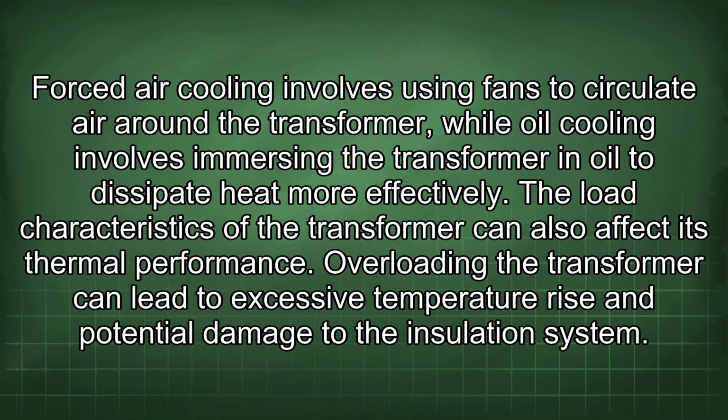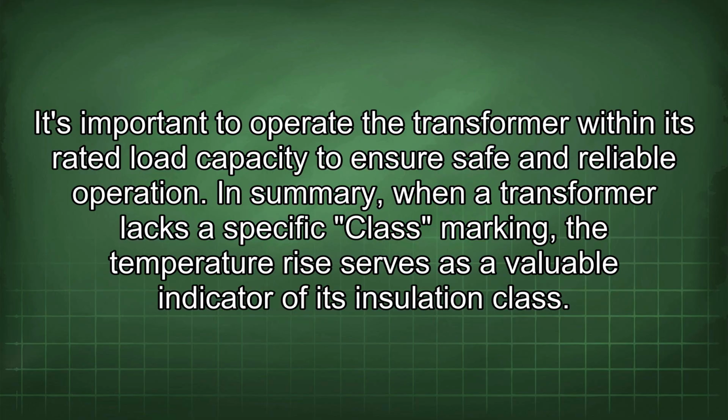The load characteristics of the transformer can also affect its thermal performance. Overloading the transformer can lead to excessive temperature rise and potential damage to the insulation system. It's important to operate the transformer within its rated load capacity to ensure safe and reliable operation.